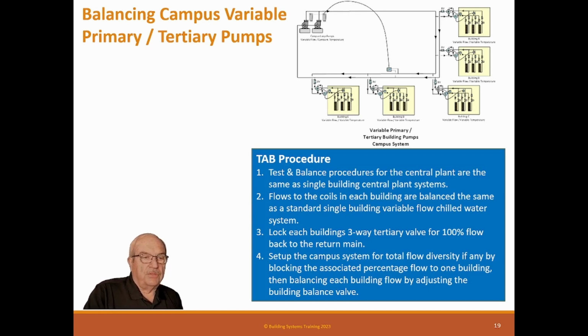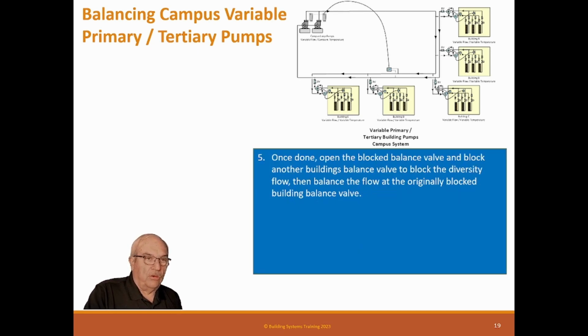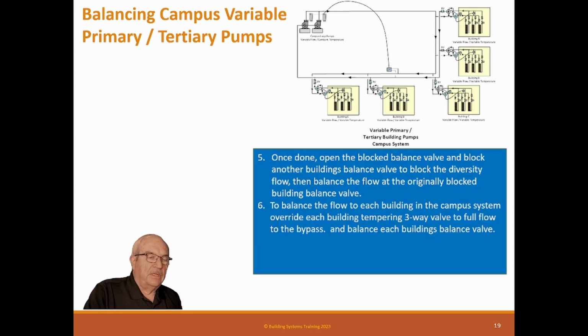And then when you're done with that, you go back and open those valves and close the other. So now you put them all balanced. You're balancing the balance valve there at the building, because we're assuming the building's already balanced. The beauty about a tertiary system is you don't have to go screw up the other buildings. You can leave them balanced. You're only dealing with what's entering the building as a tertiary pump.